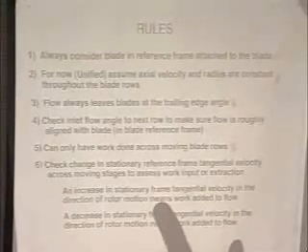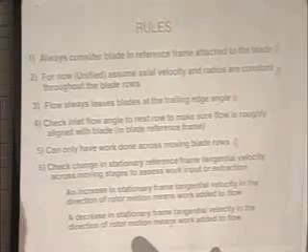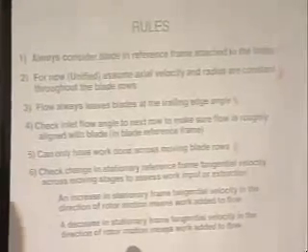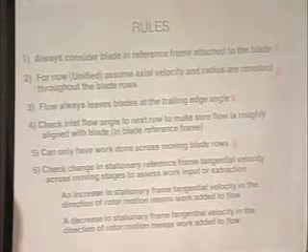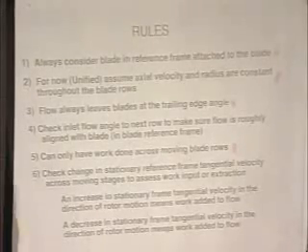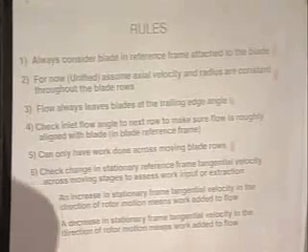And that is in the stationary reference frame, that velocity. If you know the change in stationary reference frame tangential velocity and it increases in the direction of rotor motion, that means you've done work on it. You've added swirl. If it decreases in the direction of rotor motion, you've taken work out. You've taken swirl out. So the purpose of these rotating blades is to put in swirling kinetic energy so that the stationary ones can convert it into internal energy, and you go on and on and on. All right, before I go ahead and do an example, questions about that stuff?